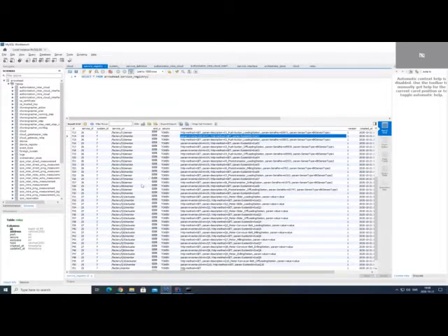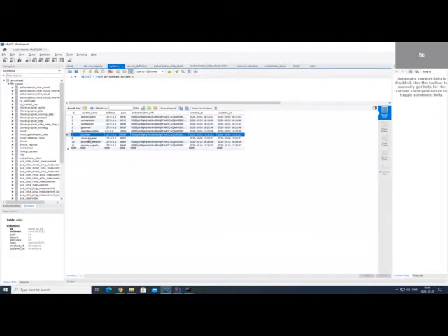For the sensor value service, we have a total of 9 service instances for getting the status of all 9 sensors, and the same applies for the actuator value service. Then for the monitorable service, we have a total of 20 service instances for getting the system ID and inventory ID of all sensors and actuators, and for monitoring the provider system. Now there is an integrator called Cloud Uploader, which acts as a consumer in the Arrowhead local cloud, and it consumes the sensor value service and sends the sensor status to another cloud in Jotne through intercloud.